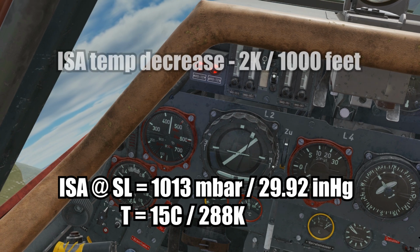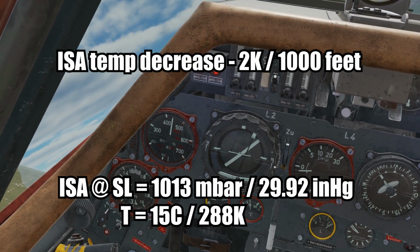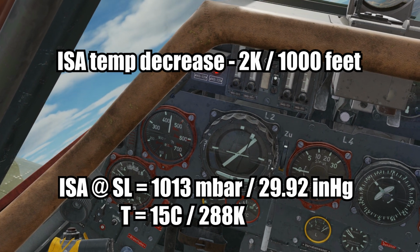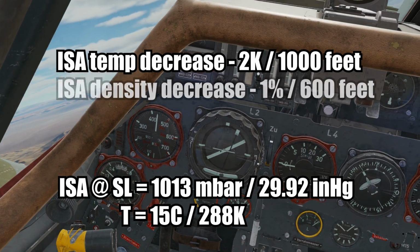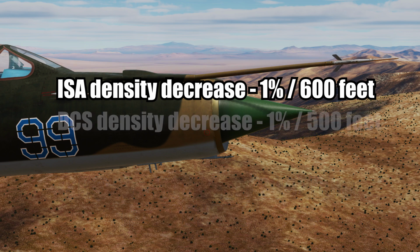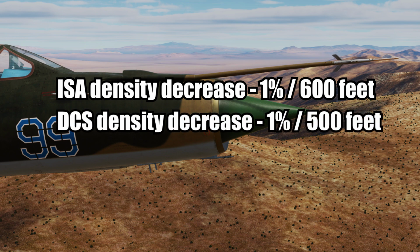As the altitude increases, the temperature will drop by 2 Kelvin, which is the same as 2 Celsius, for every 1,000 feet increase in height. The density will decrease by 1% for every 600 feet increase in altitude. DCS actually calculates this at 2% for 1,000 feet.